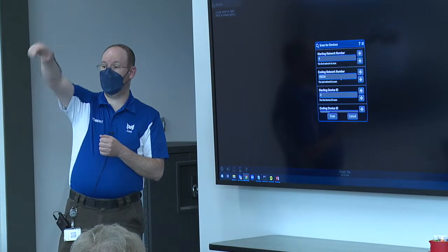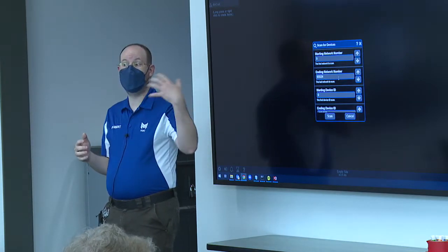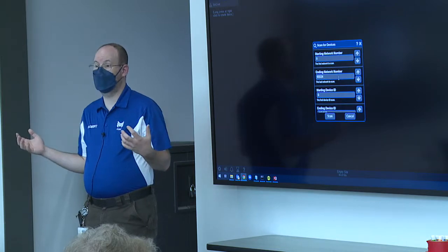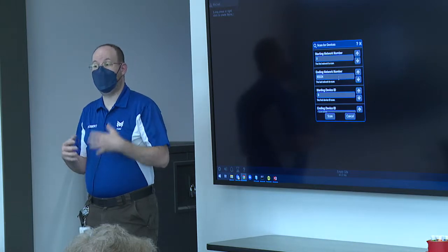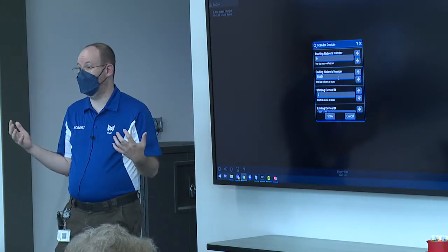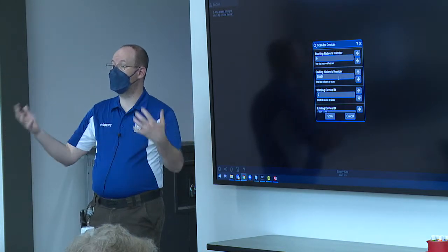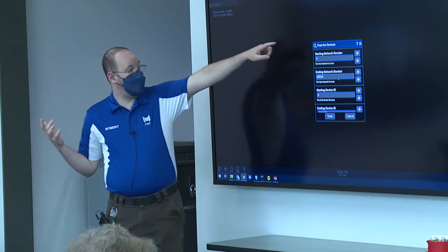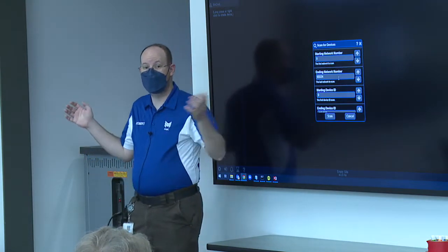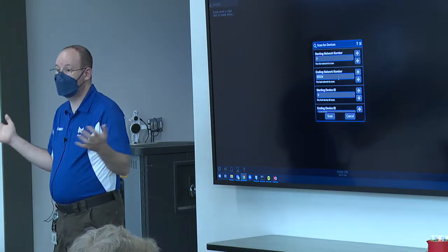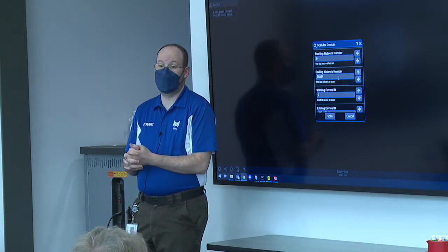So on the back table behind Lanny, Sean, and Russell, there are some VAV controllers that are using MSTP. We have a router that's connecting our IP network to that MSTP network. That MSTP network's number is 201. Okay? I know that because I'm the one who set it up. If you don't know that, you've got to scan a whole lot of networks. The 65,000, that's 64K options. So that's how many networks you can have on a single BACnet system.